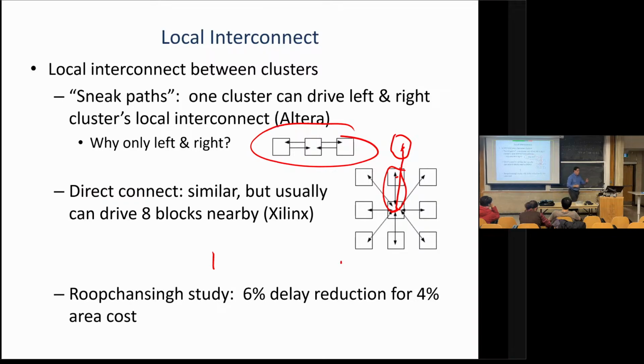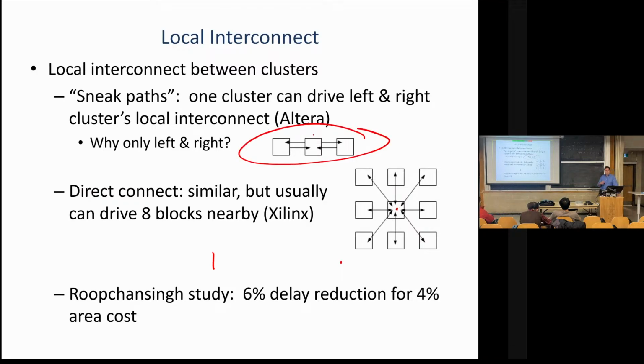So that vertical wire would become a lot longer, and you'd get some extra muxing and so on. So it's possible to do, but it's just not worth it. So basically you'll see that in Altera architectures, they prefer to do things horizontally. And it's because horizontal is cheaper, because the redundancy always shifts only up.